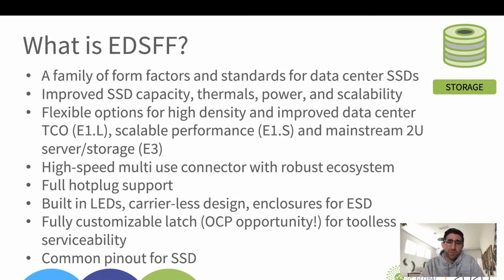You have this high-speed multi-use connector with a robust ecosystem. We're going to go through all the different ecosystem and OCP parts that are using this connector, which is called the SFF-TA-1002 connector. You have full hot plug support across all the different EDSFF form factors. One of the unique things about the EDSFF form factors is the drives themselves have built-in LEDs. They have a carrier-less design. Now you saw there is an E1.S that has mounting holes for a carrier, but you have standard options with an integrated enclosure that actually has the LEDs and the enclosure and everything built into the SSD.